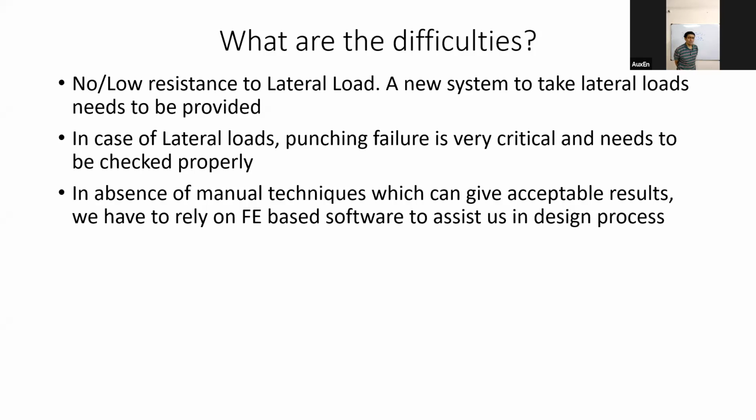So this is another difficulty that we face when we are providing flat slab systems. Flat slab systems, I will say, are not very good systems to be provided in high seismic zones. They are not good systems. Even if you are providing shear walls, still the inherent disadvantage of flat slab is that it is not a very good system for high seismic zones. And in high seismic zones, going to a very great height, flat slab systems are not for you.